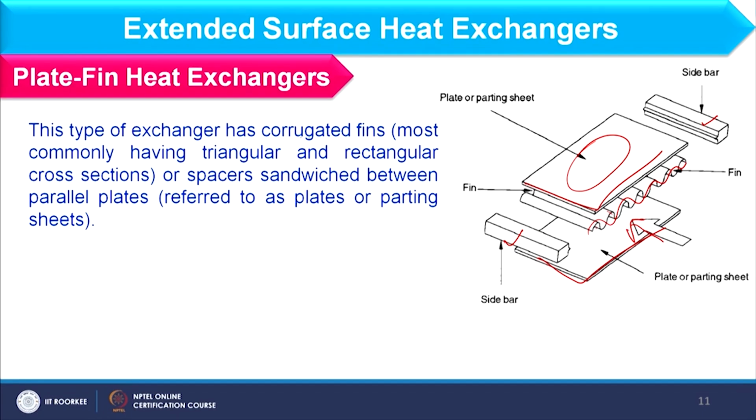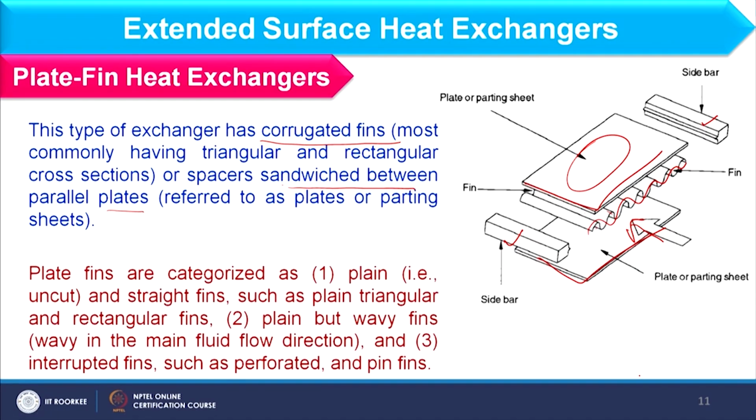This type of exchanger has corrugated fins or spacers which are sandwiched between parallel plates, as we have just discussed. Plate fins are categorized as plain and straight fins, such as plain triangular and rectangular fins, like we have this type of fins or this type of fins. So, this is the rectangular and triangular type of fins, and in some cases it is wavy fins, as we can see here.